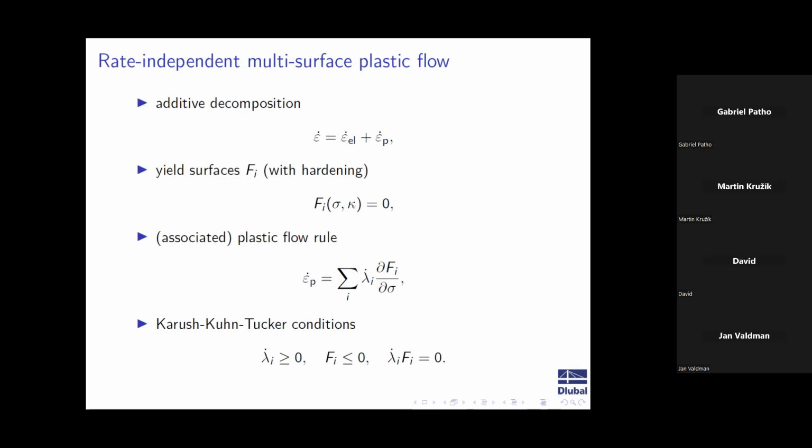These can also change in time, although I'm here referring only to some pseudo time because we are in rate independent evolution, so no inertial effects whatsoever. We apply our classical plastic flow rule with the plastic multipliers lambda I, although I can also have non-associated plasticity where the plastic potential does not need to be Fy.